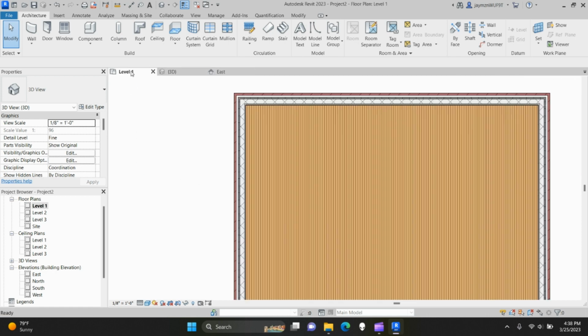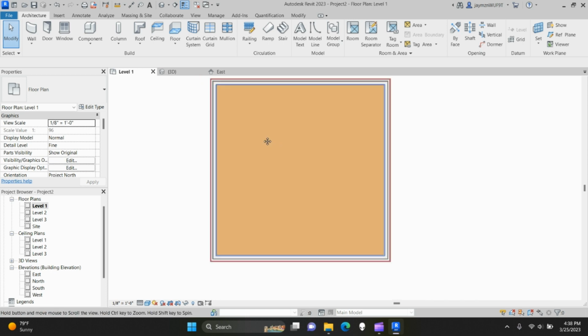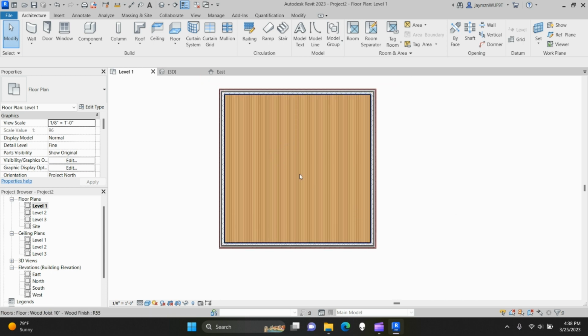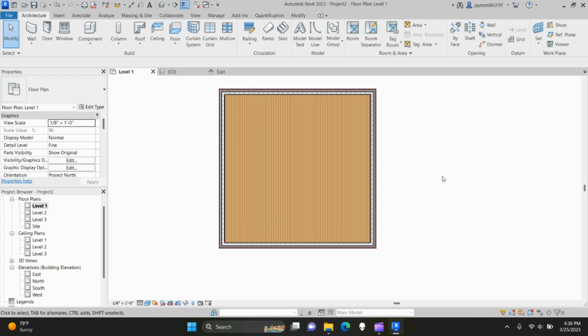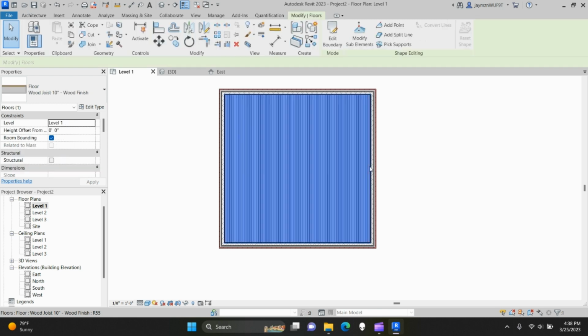And so I'm going to go back in here. So level 1, if I'm just on this right here, I can click and there's my floor. But what I was talking about, the tab key. So if I'm over here, I can tab, select all the walls, tab again, back to this wall. And if I try and bring it to the edge here and cycle through with tab, there you can see I can click the floor that way too.